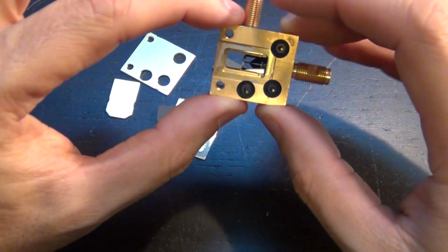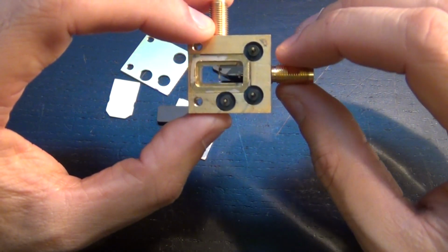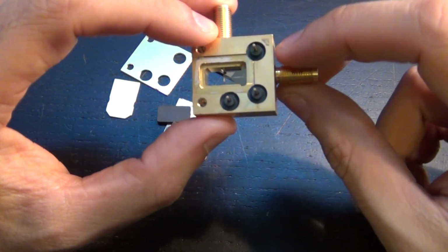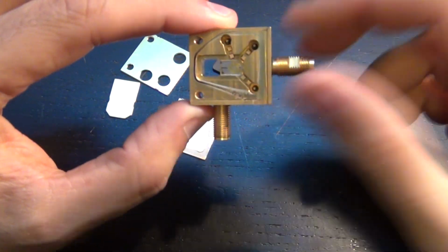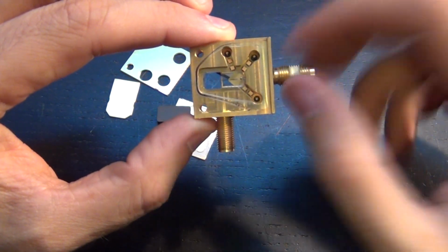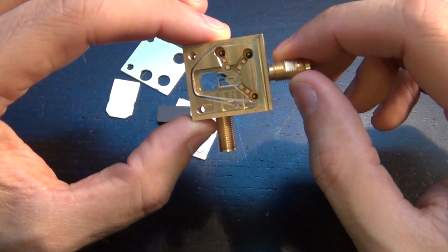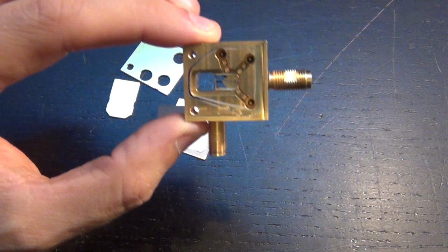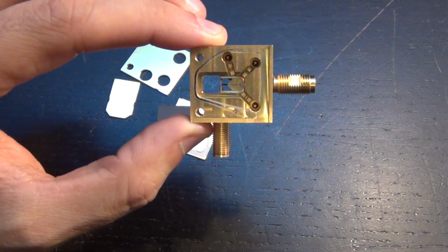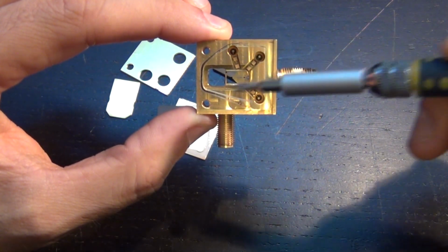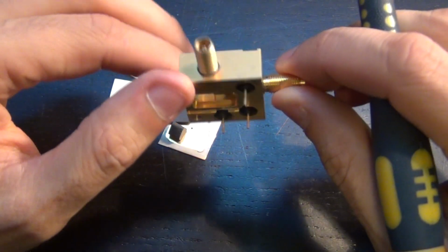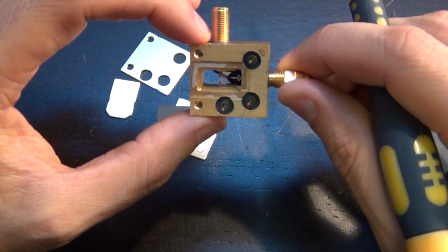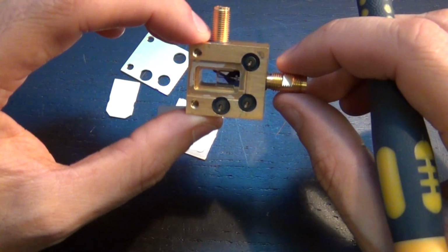And check it out, it's really neat. The substrate, which is most likely quartz in this case, is transparent. So whatever material they're using and whatever exotic technology they're using is directly on top of this quartz substrate carrier there, and everything else is gold plated. You can see various different wire bonds going from the different pins onto the main carrier there. We'll look at this under the microscope. I just wanted to give you a global view of how it looks, completely and utterly custom made.